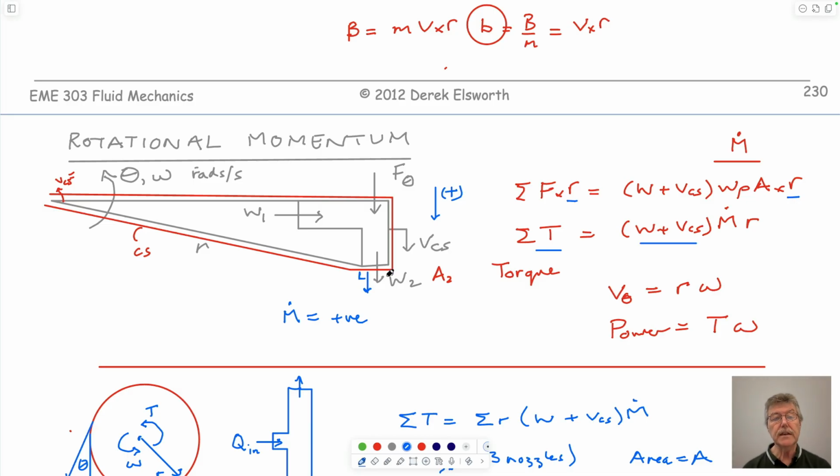And if you wanted to calculate the power, as we did last time, when it's held static, the power, since it's equal to the product of the torque and the rotational speed, is 0. Allowed to rotate at its own velocity, then the torque is 0 because you're letting it rotate, and this is a maximum, but still the power is 0. And so somewhere in between those two, when you attach an armature to it to generate electricity, then you get the maximum, you actually get power out of the system.